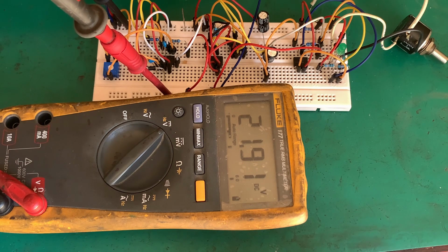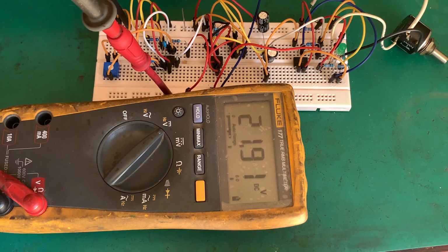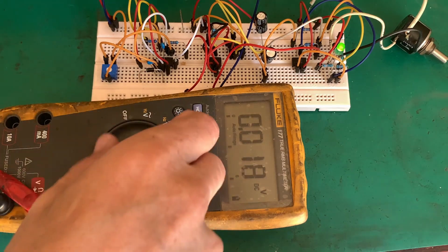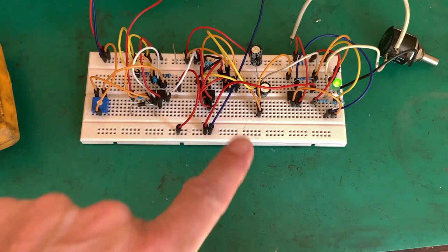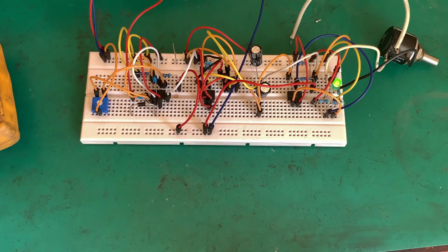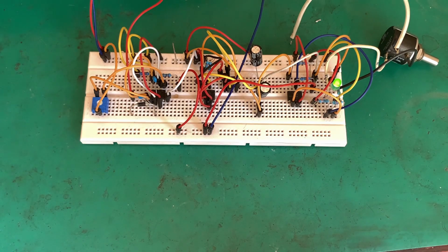My MC34036 is now getting to its minimum, so it's starting not to work very well. But anyway, 22, bang, there we're on. Well, 24. So you see how useful op-amps can be. Even the LM741. Create yourself a split rail and off you go. Problem solved of the rail to rail voltage. Well, almost. You can have other problems. So anyway, let's wrap this up.